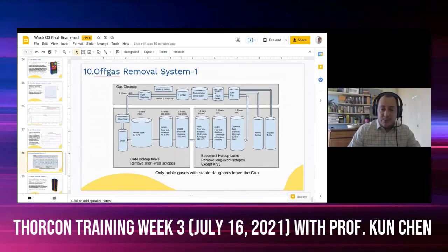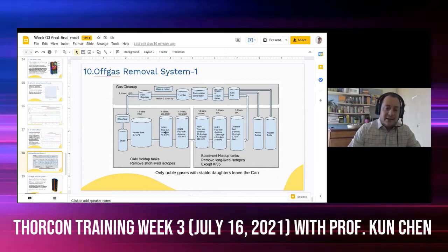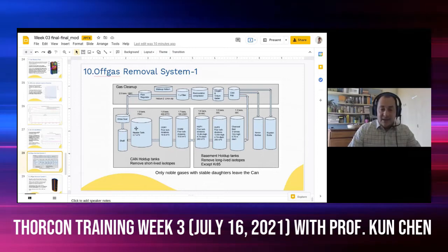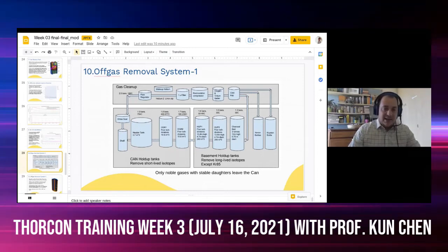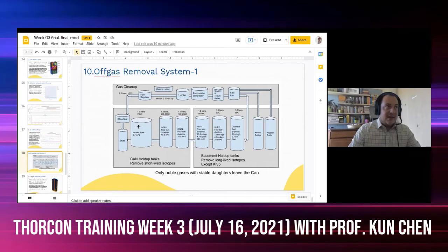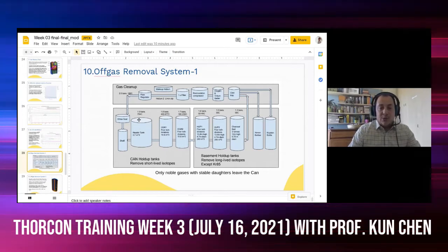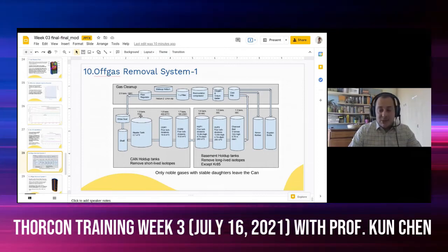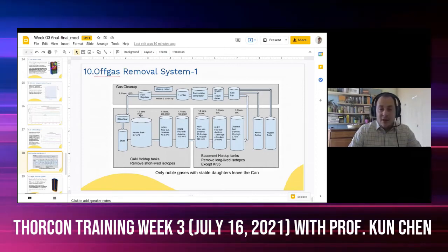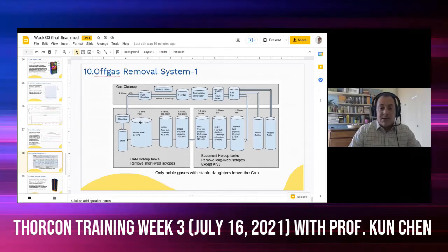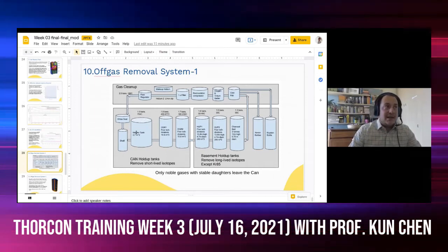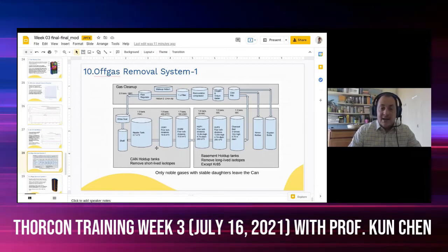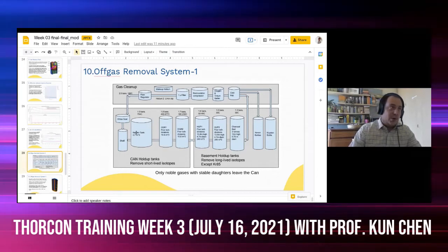gaseous fission products to leave the header tank is quite large. So a lot of decay happens inside the header tank, but outside of the core. So the non-gaseous daughters of gaseous fission products, in most part, do decay inside the header tank and go back to the salt where they stay as soluble fission products.